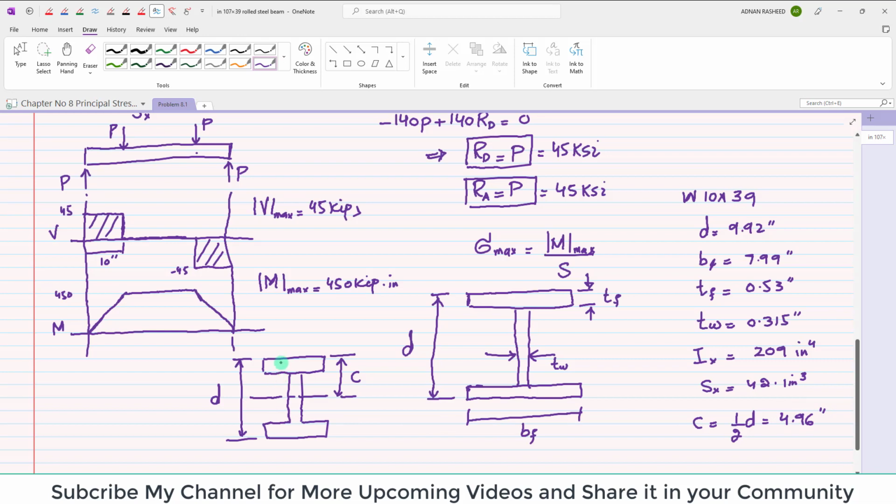Similarly, this is the top of the flange. Let's say the junction of this flange and web is point B. This height will be YB, and this YB is equal to C minus the thickness of flange TF.